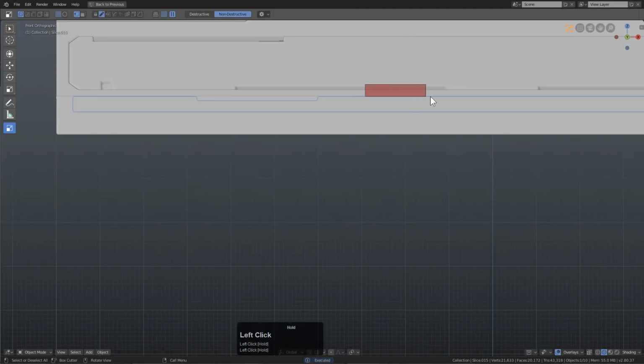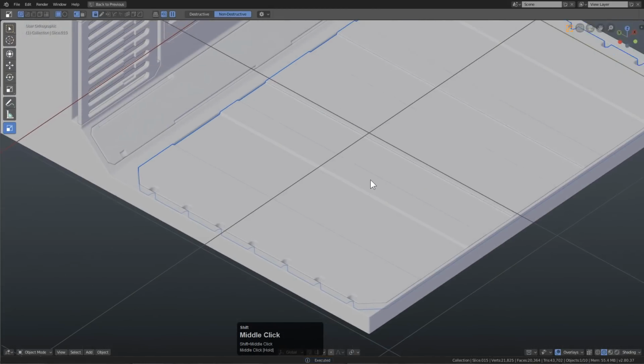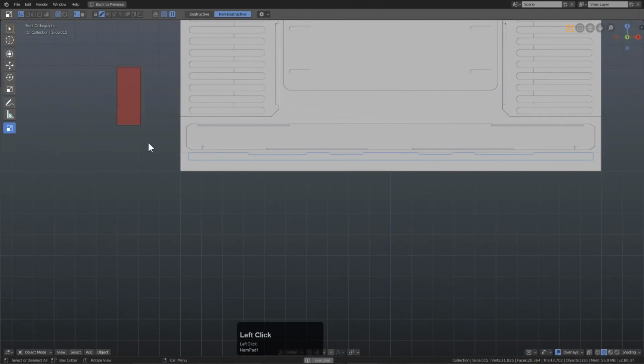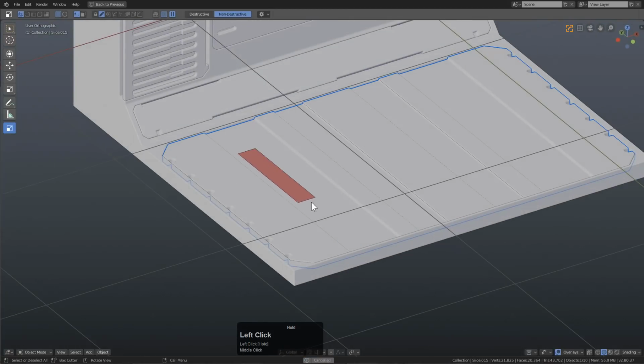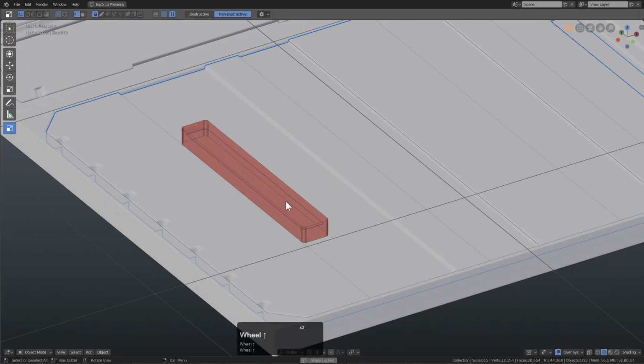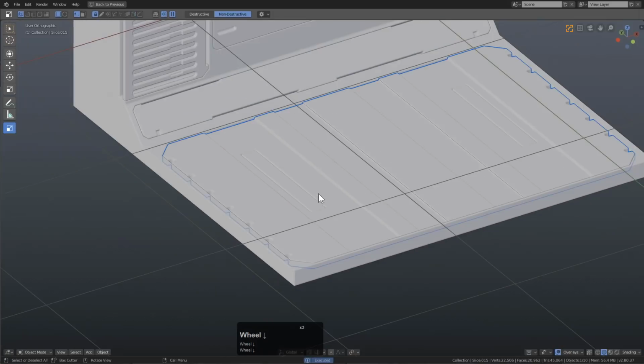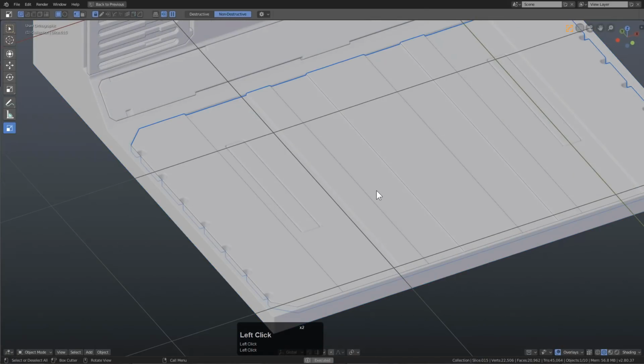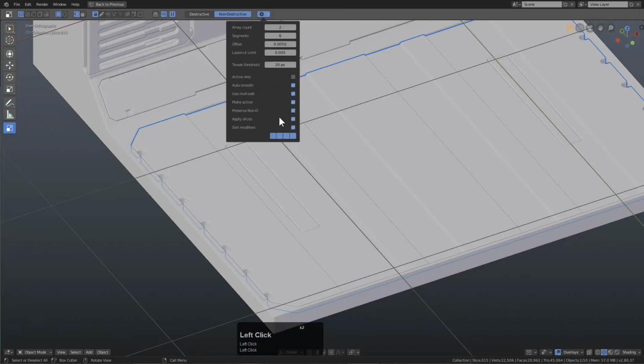So we'll just cut a few little slats in front view. With Boxcutter, basically, if you draw starting off the canvas, you draw a 2D box. But if you draw with your cursor over the mesh, it's going to give you a 3D box. And you can always disable that using this option up top, which will align the shape. But really, I just stick with the defaults generally. But just know that we have more than enough behaviors here to allow you to set it to what you need.